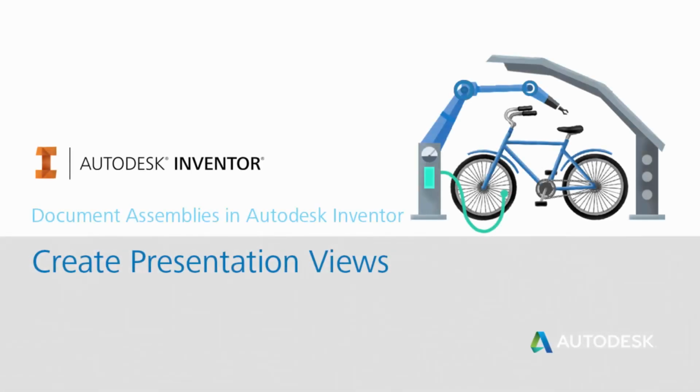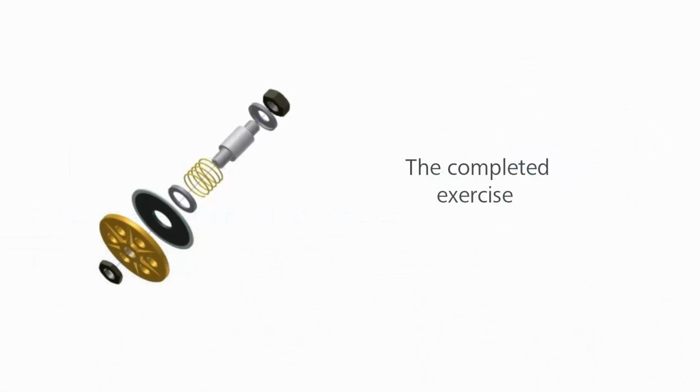In this exercise, you create a presentation view of an existing assembly in a new presentation file, and then you add tweaks to the assembly components to create an exploded view. Trails are automatically created when tweaks are applied to components. As all the tweaks follow the same path, there is no need for trails to be displayed for all the components. In this exercise, you display the trails for the first 3 tweaks you create, and then you turn off the display of trails for the remainder of the tweaks.